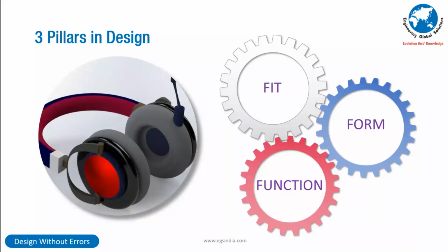Remember, every consumer of your engineering drawing is internal as well as external. If the general arrangement drawing has to be blessed by the customer before you sign off, it gets consumed by the customer. Otherwise, the stakeholders inside the organization are the predominant consumers of your drawings. So any mistakes that you do on the drawing, it could be fit related, it could be form related, it could be function related. Finally, it translates into quality issues and reliability issues.